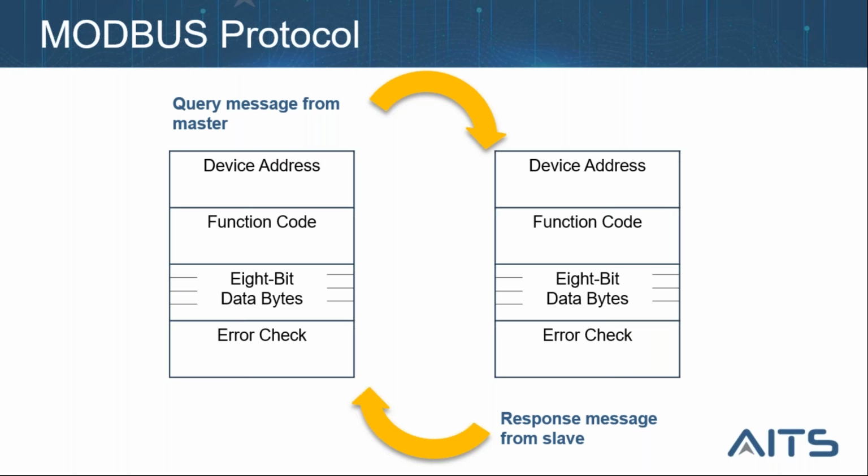Typical master devices include host processors and programming panels. Typically, slaves include programmable logic controllers. A version of the Modbus protocol exists for serial port and for Ethernet and other networks that support the Internet protocol suite. There are many variants of Modbus protocols such as RTU, ASCII, and TCP/IP.